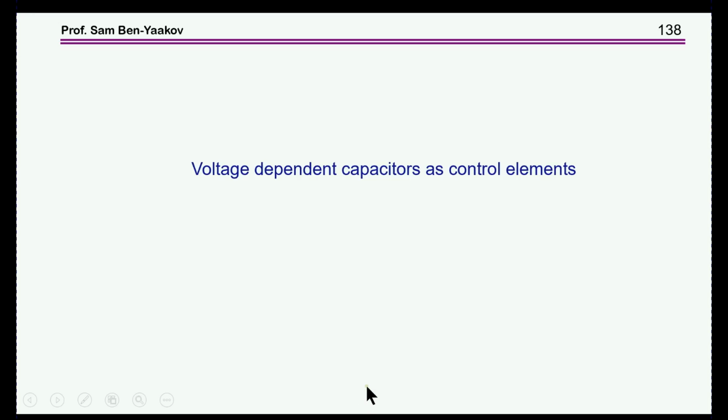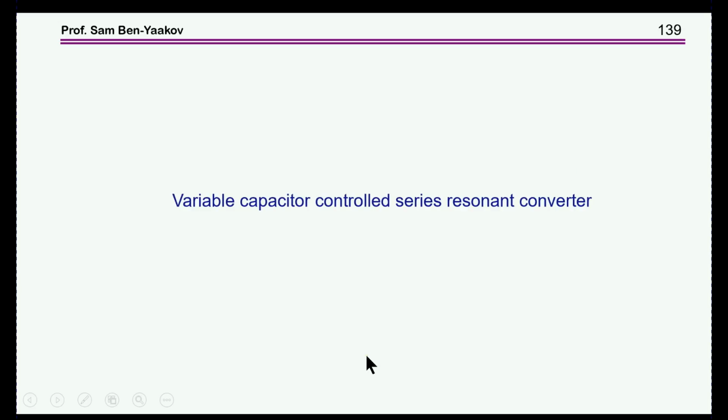So some time ago, I decided to look at this possibility of using the nonlinear effect, the voltage dependence of the ceramic capacitor, to build converters in a different way. So the first one that I'm going to show is the series resonant converter.